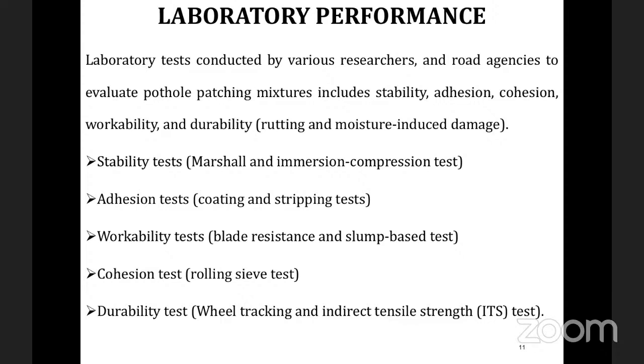I think you know what rutting is. Rutting is the wheel depression along the path that happens due to the wheel load. Moisture damage happens due to water. As I told you in the starting slides, water and traffic are the main culprits, so we have to look into the durability properties, that is, rutting and moisture-induced damage.